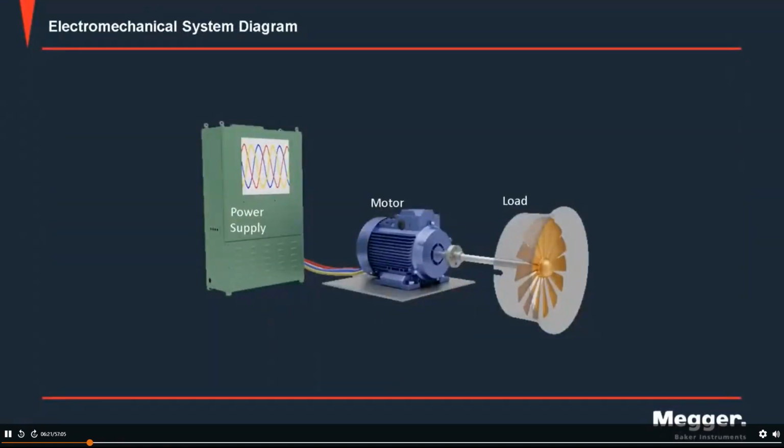Okay, so as you're probably all aware, when we're talking about motor testing, we're not just concerned about the motor. We're concerned about the motor and the insulation of the motor, bearing health, proper cooling, all that stuff. But we also need to be concerned about the quality of power that we're feeding the motor, how we're loading it, and that the motor's properly applied for the job that it's being required to perform.